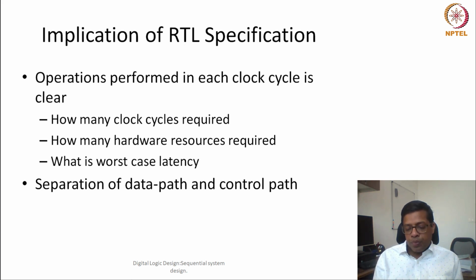period. So that also has an interesting implication: if we know all the resources, all the hardware components, that also means we know the worst case latency. Between any two registers, what is the worst case delay, what is the maximum delay from one register to another register, can also be computed at the RTL level of design.